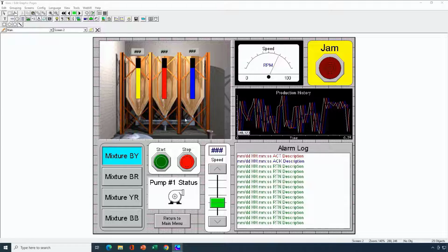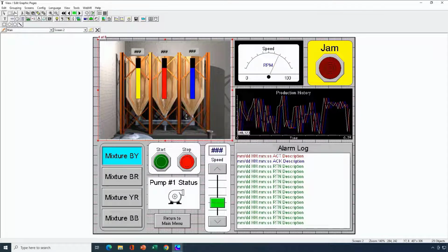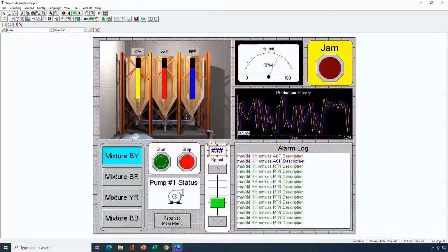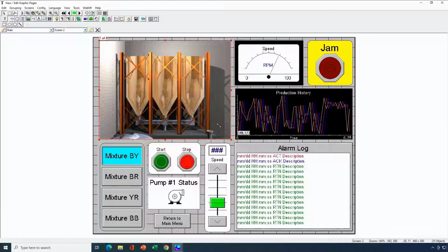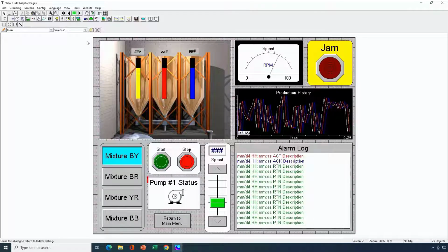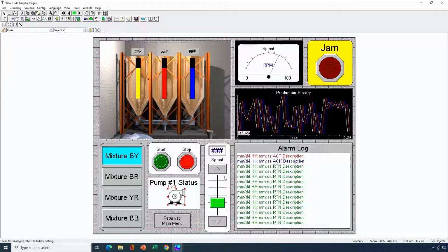So I'll double click on this graphic object here, which is showing up as a text object. So it's buried within this, and I'll hit the tab button until the graphical object is displayed. So here we are, and now I'll send that to the back. Now I have my bitmap object and I'll select Scale to Fit. I'll send it to the back again so that the other objects in the front will be where they need to be. This is a bitmap object here as well.